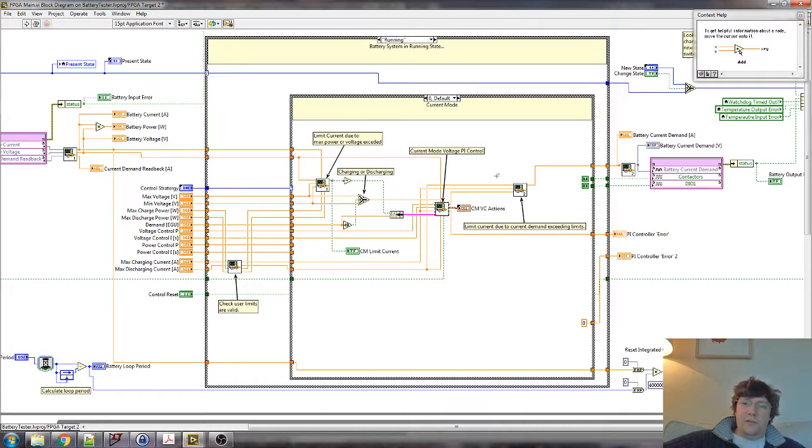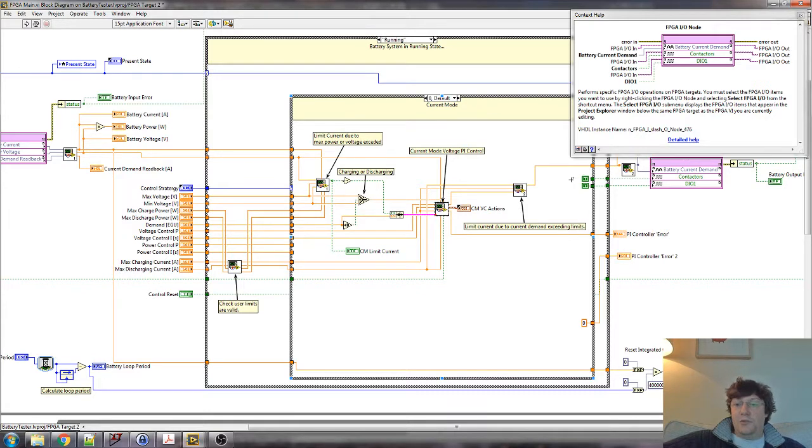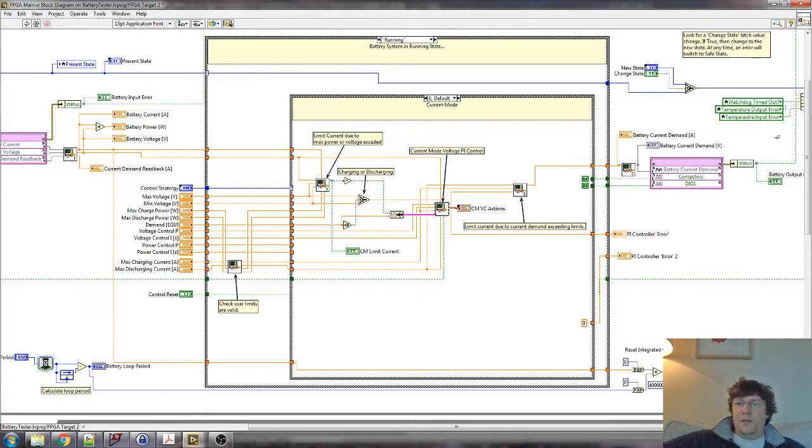So our embedded system has to present that small voltage as if it is that current. So when we're thinking about our outputs, it's a current demand. Even though it is a voltage, it represents a certain current, and the representation is the gain of the power electronic system. So that's our setup for the current mode.